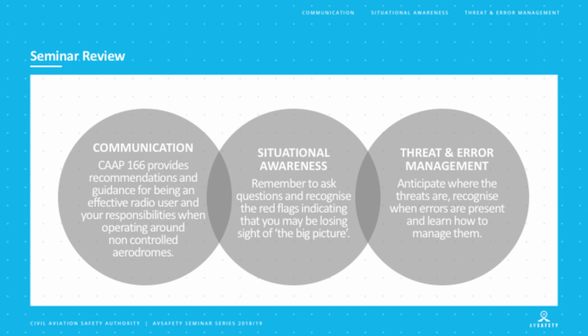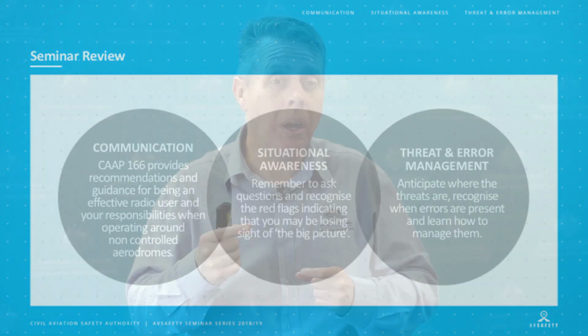Secondly, that communication led on to the building of situational awareness. Remember, we spoke about that 3-step process. Where has the aircraft been? Where am I now? Where will I be into the future? A process that doesn't come naturally, but as we gain more experience, becomes more and more intuitive to the pilot. With situational awareness, it's that one thing that will help us keep ourselves safe and alive at these non-towered aerodrome environments.